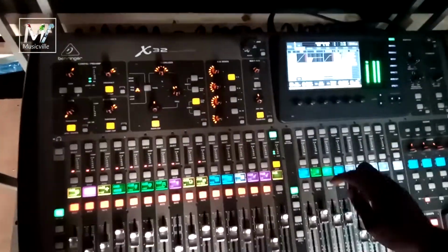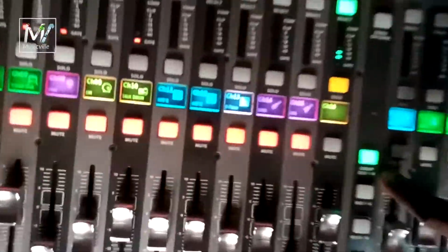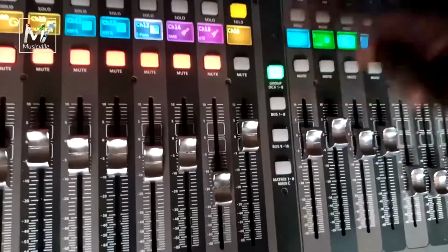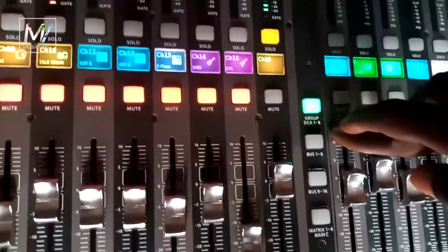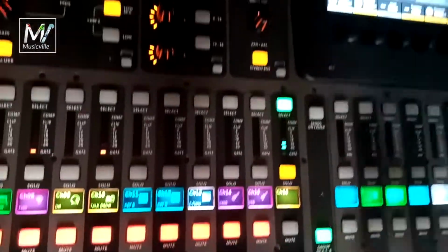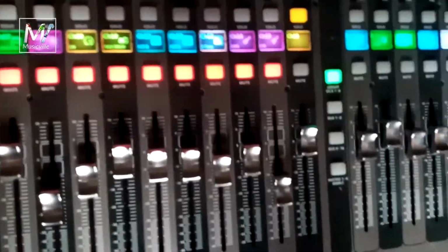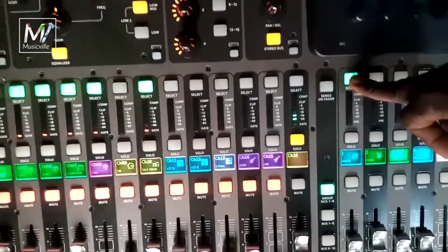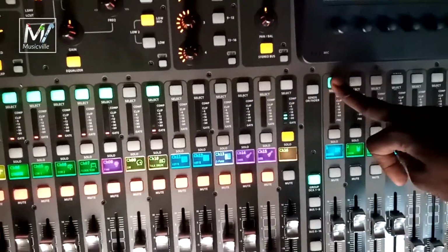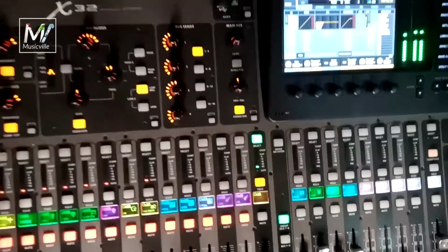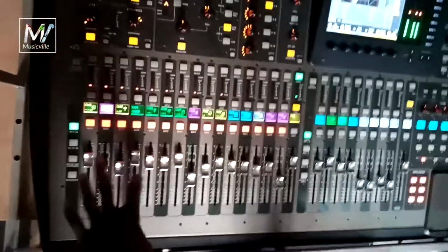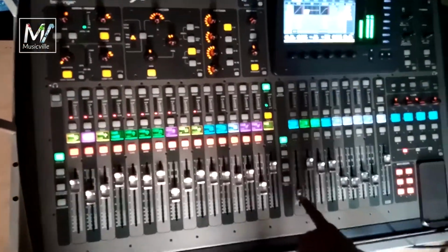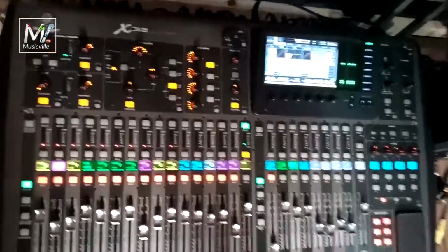And then, one more thing on the DCAs. This is a DCA or a group DCA. This means digitally controlled amplifiers. That's the meaning of DCA. So this is equivalent to the groups on an analog mixer. For example, this has 8 DCAs. So I can assign every drum to DCA 1. This gives me an opportunity to turn up and turn down the volumes of the drum. Maybe the drummer is playing too loud. Instead of turning them one by one and affecting my mix, I could just turn down the entire drum at once. I could just mute the entire drum. This is another way to mix.